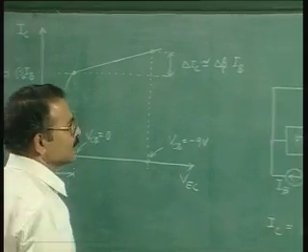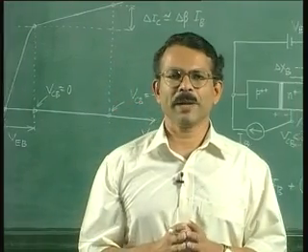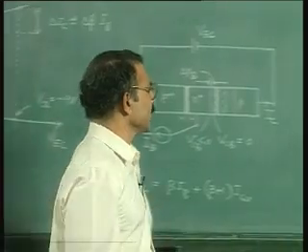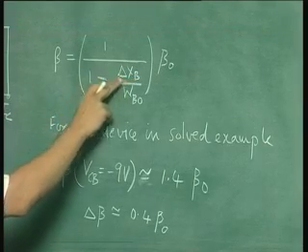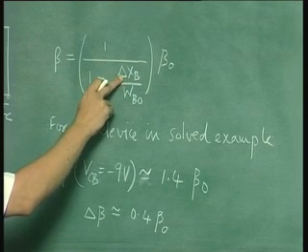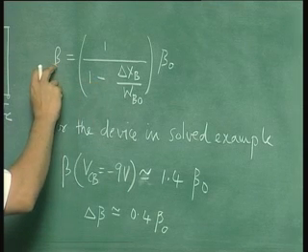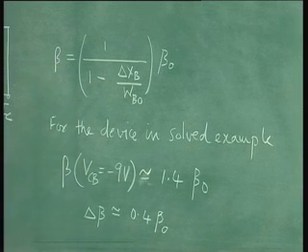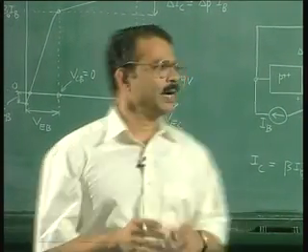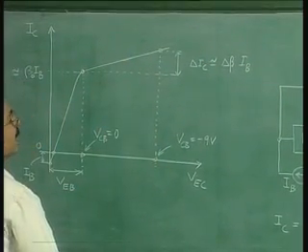So this obviously means that the practical transistor for which those current voltage characteristics are obtained has a higher value of doping in the base. Okay, when the doping in the base is higher, then this delta XB will be lower, the modulation of the base width would be lower, collector base depletion region will be smaller. So therefore the beta will not change that much with collector base voltage. Okay. So this is how the base width modulation and the slope of these characteristics here is related to the doping in the base.